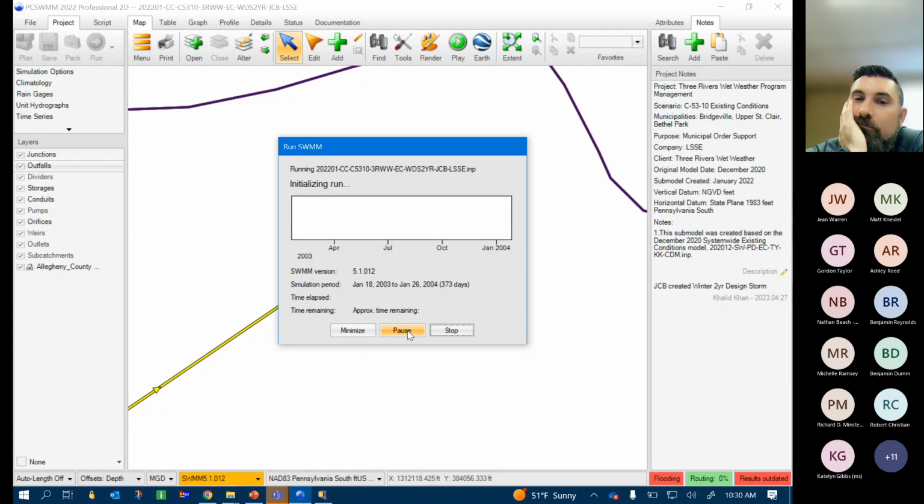You have to run it up. It's not a long simulation, you only need a day or two. It just wets the system, fills those pipes, and gets the simulation ready. If you make any changes to the collection system or your hydrology or really any changes to the model, I would recommend that a new hot start file be created and rerun.